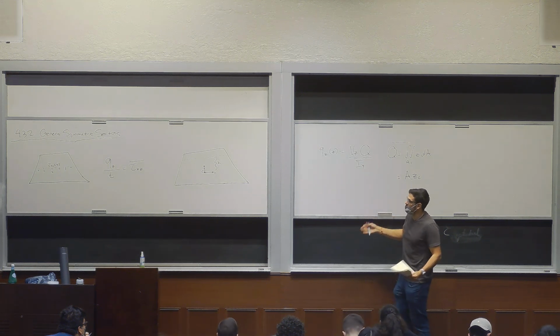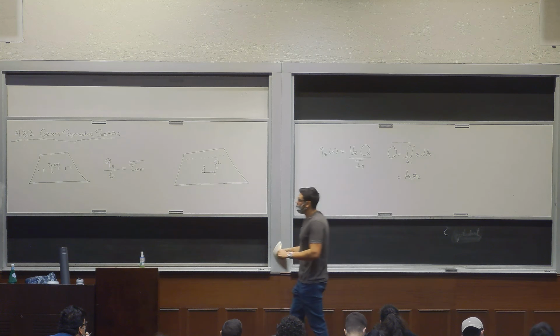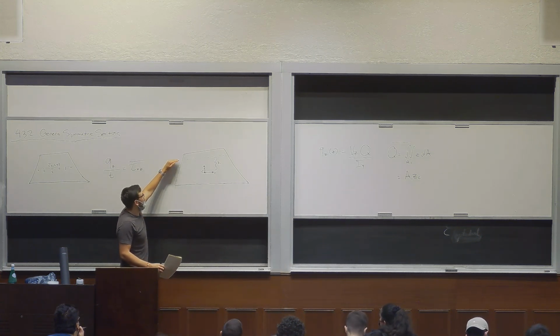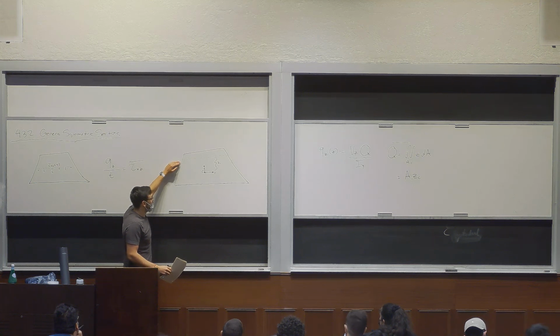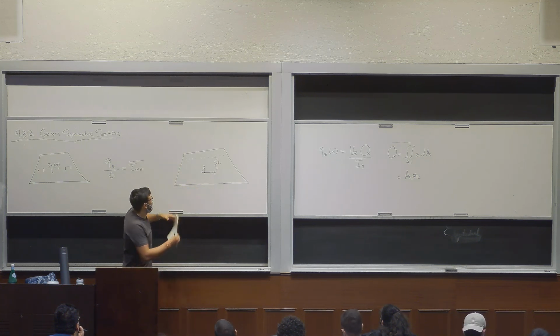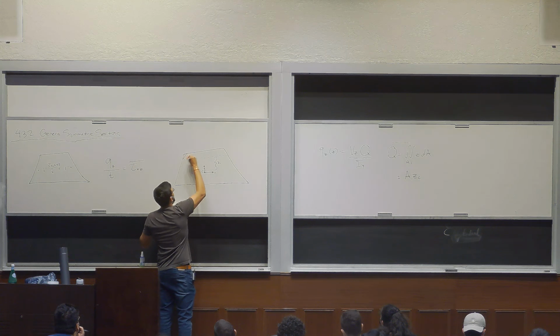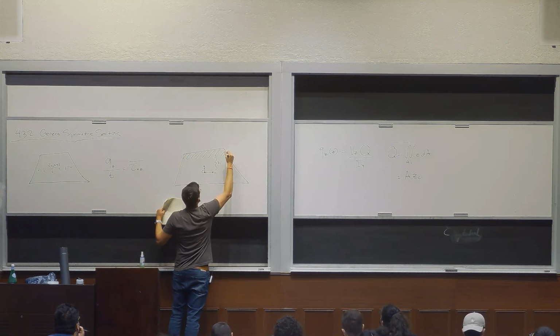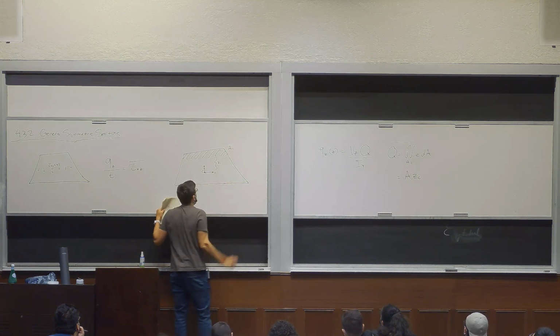Okay, so what is that Q? That's known as the first moment of area. So you would basically make a cut at whatever location you're interested in finding Q at, right? So let's say we're looking for the shear flow at Z1. We'd make a cut at this position, and then the area above this cut, right? That would be, let's call it area 1.